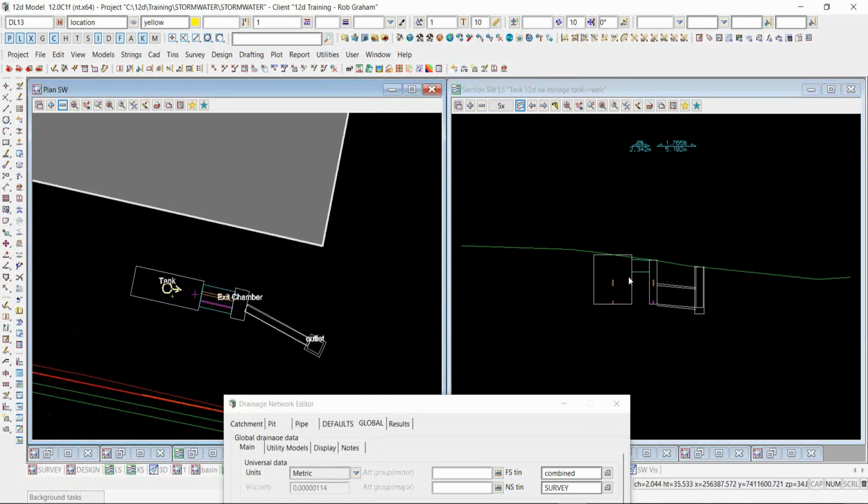And you can see what we have here is this is the storage tank. The storage tank on the weir path, you can see there's my weir. It goes and drops down into my outlet pipe, which goes down to my outlet down here. Now, when you're looking at the weir path, you can also see the elevation of two other flow paths. There's a pipe that goes across here, and there's also an orifice down here across the bottom. So what I'd like to do is I'm going to go take a closer look at those to give you an idea of what's been taken out of the library.